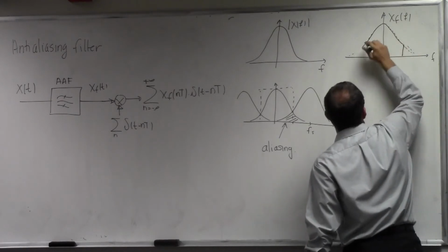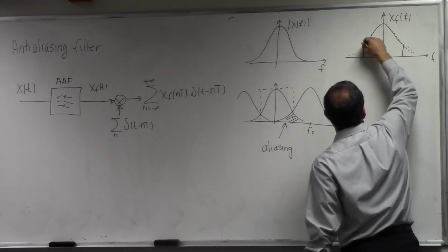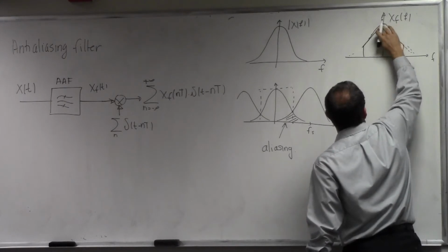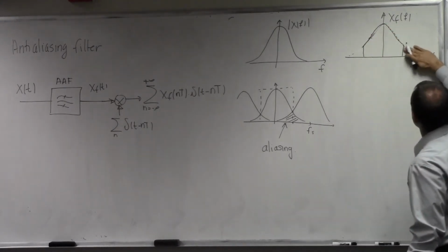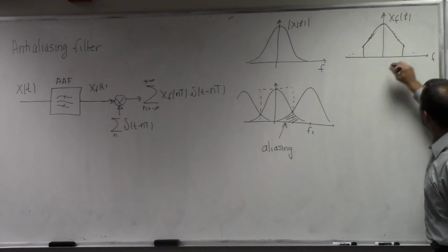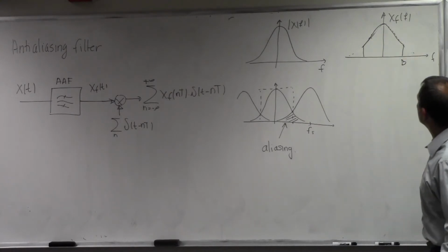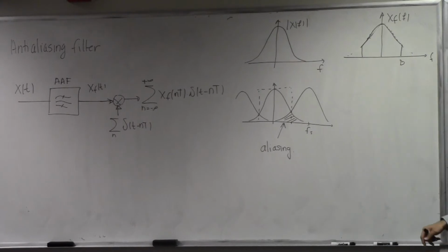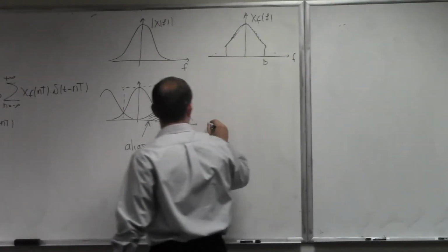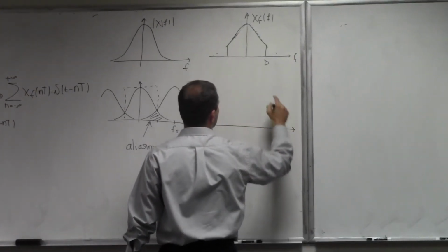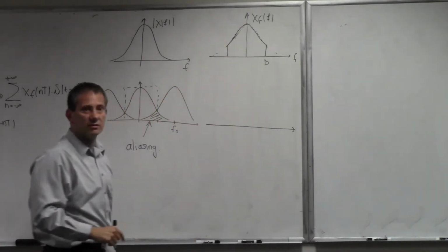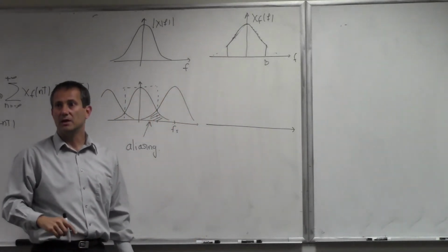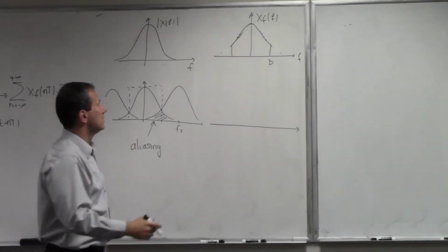Right, and I'm kind of exaggerating here so that you can see the drawings, right? So I got rid of all the high frequency components, and my signal now occupies just from here to here, right? And this is what we call bandwidth. The bandwidth is now defined by us and within our control, because we got rid of all the components that are outside. This makes sampling quite easy because now I know that if my Fs is larger than this well-defined bandwidth B, there will be no overlap in the spectral domain.